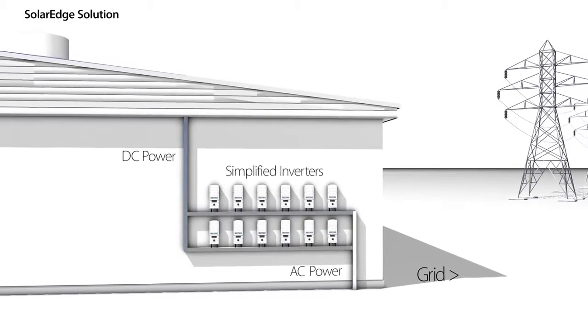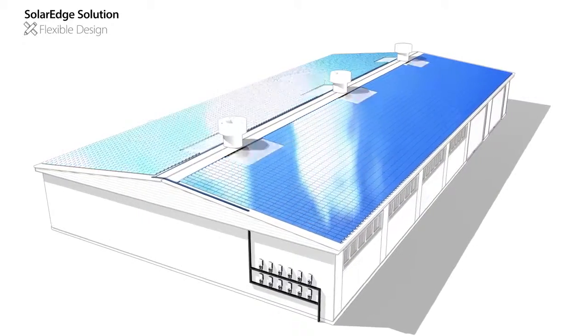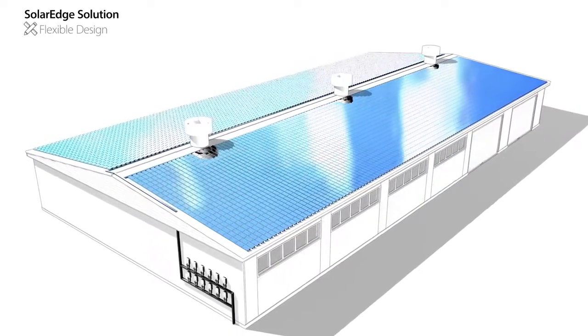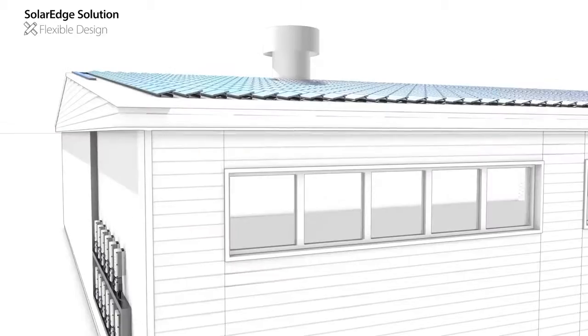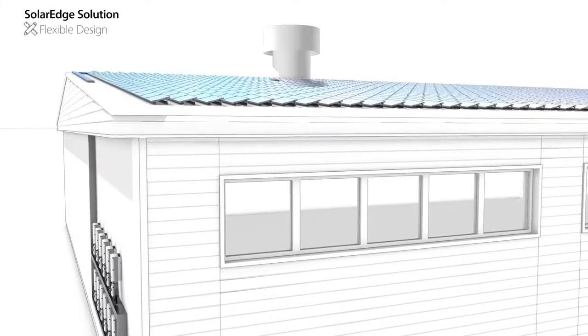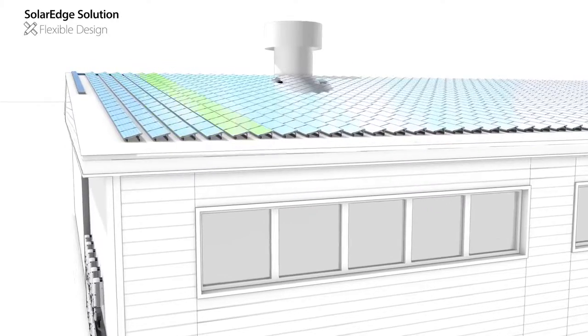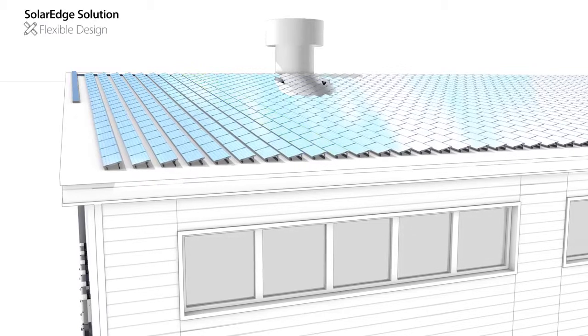inversion and grid connection. In comparison to the limited design of string inverters, designers of SolarEdge commercial systems enjoy great flexibility and are able to fit more panels in a given space. Additionally, the SolarEdge solution enables connection of much longer strings. This significantly lowers the number of strings per system and reduces balance of system costs.